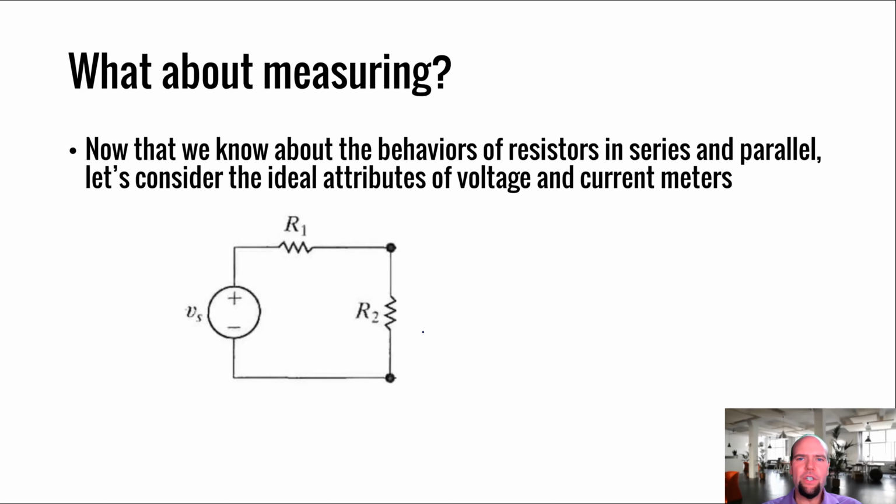So if you're measuring voltage, what is voltage? Voltage is an electrical potential between two different locations, right? It's a potential difference across things. And because voltage is this potential difference between two locations, your meter is going to have to connect to measure voltage. If we're trying to measure the voltage across R2, your meter is going to have to touch